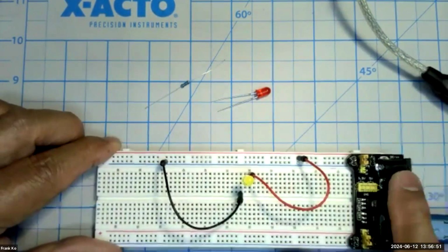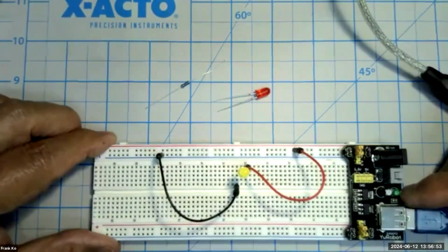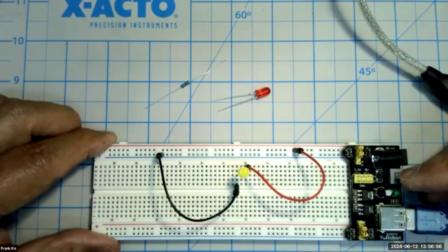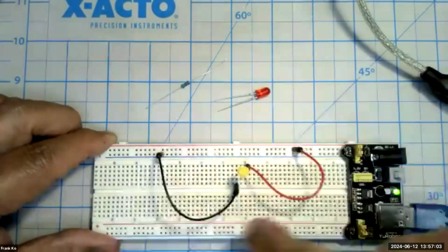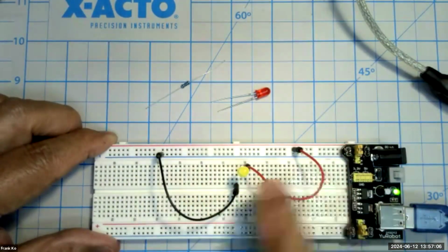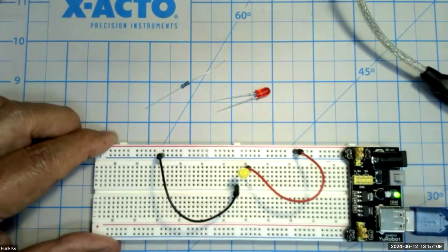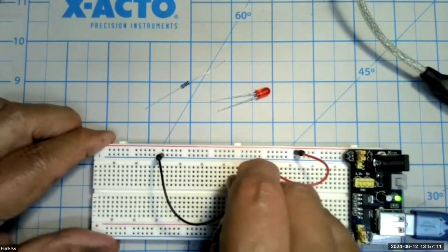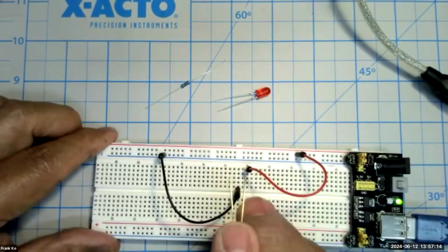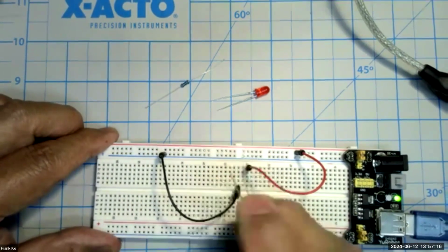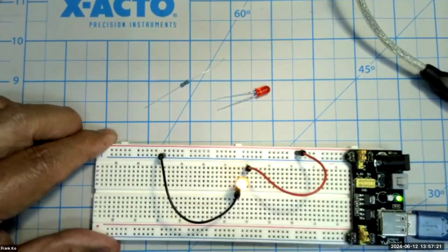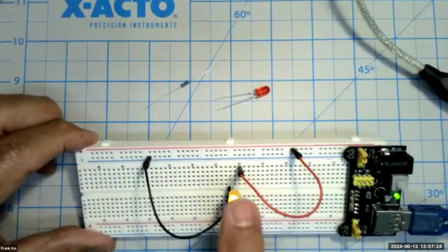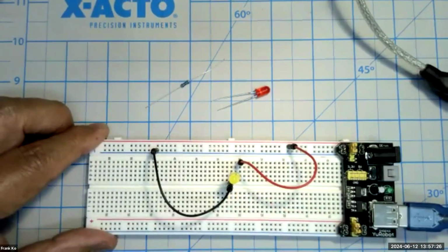I'm pressing the button. And as I press the button, watch, the LED on the power supply board is off, meaning my switch is off. If I press the button, this LED is on, which tells you the power supply is working, but there is no continuity in the circuit because the LED is backwards. If, however, I leave that on and flip the LED around the way it's supposed to be connected, long lead on pin 30C, and the short lead on, watch, boom, it lights up beautifully, okay? So that's one reason why the circuit may not be lit up.